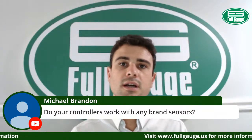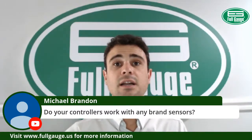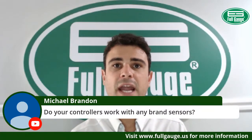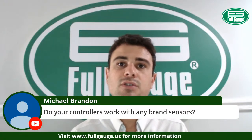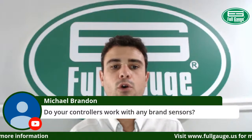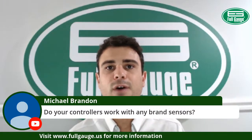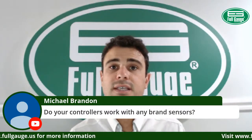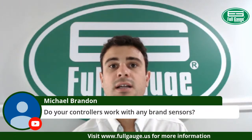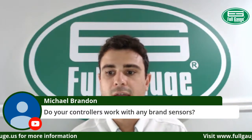The sensor reads a certain temperature when it is at a certain resistance in ohms. Most controller manufacturers use 10,000 ohms at 25 degrees Celsius. That's what we have for our temperature sensors: 10K at 25 degrees. However, outside the 25 degrees range, you might have a temperature difference because the curve is not the same for every controller manufacturer.